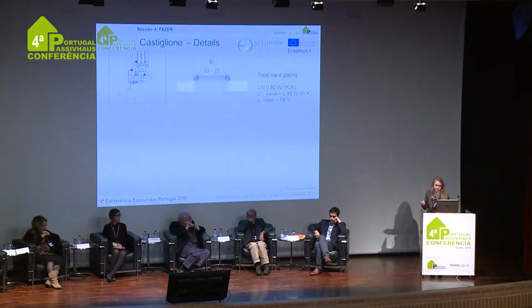To be honest, we usually recommend windows to be installed aligned with the insulation layer. So here I wonder if we would have done it, installed the window in the insulation layer, it wouldn't have been enough to have double glazing. But it's up to everyone to use the solution they would like, as long as they respect the final criteria in PHPP.